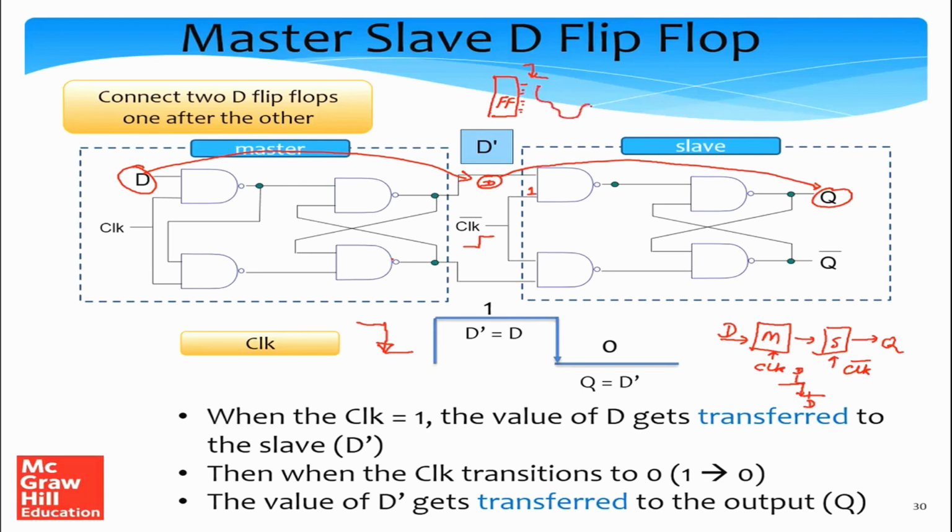We'll then have a set of logic gates. It's typically represented as a cloud like this of logic gates. They'll compute their value within the clock cycle, and before the next negative edge, the values will be ready, and they will then be stored in one more flip-flop, right?